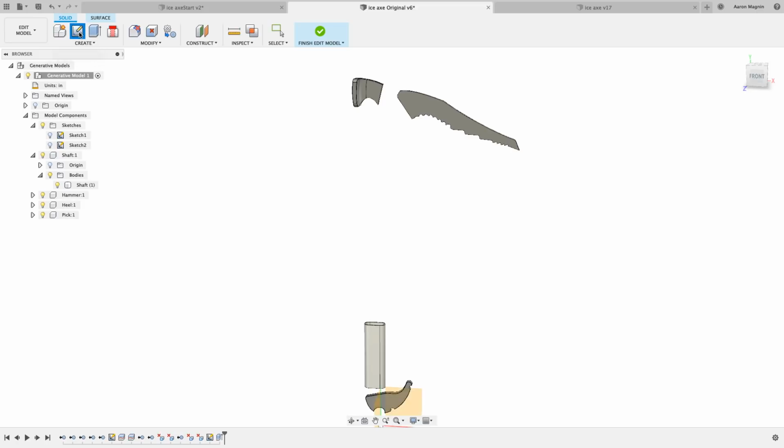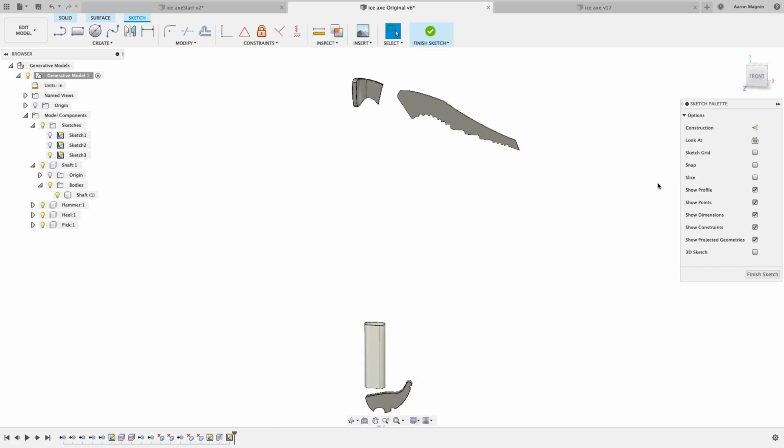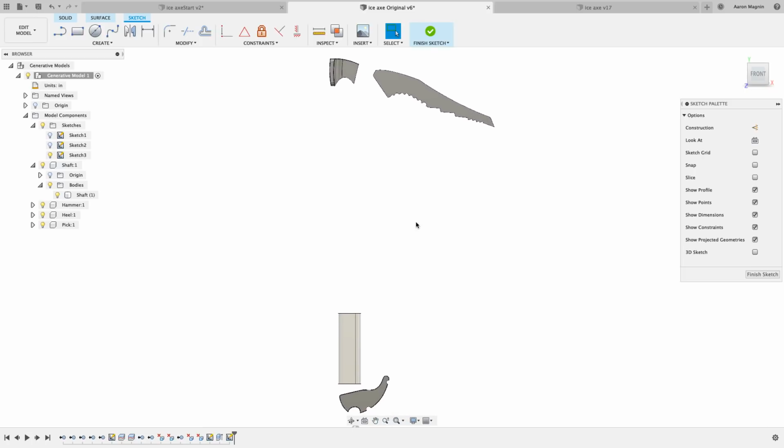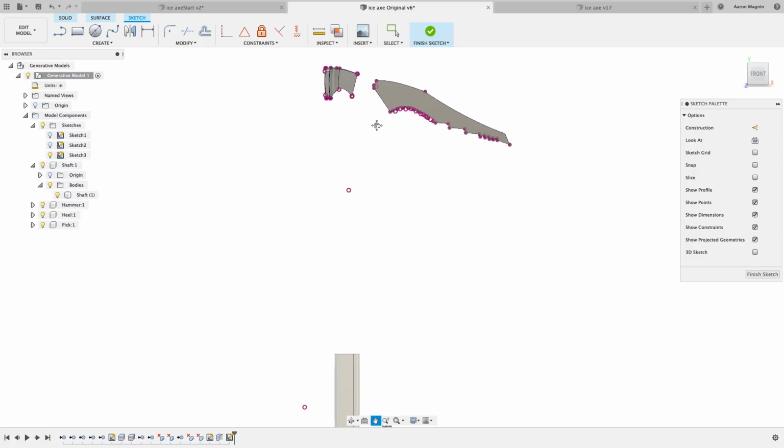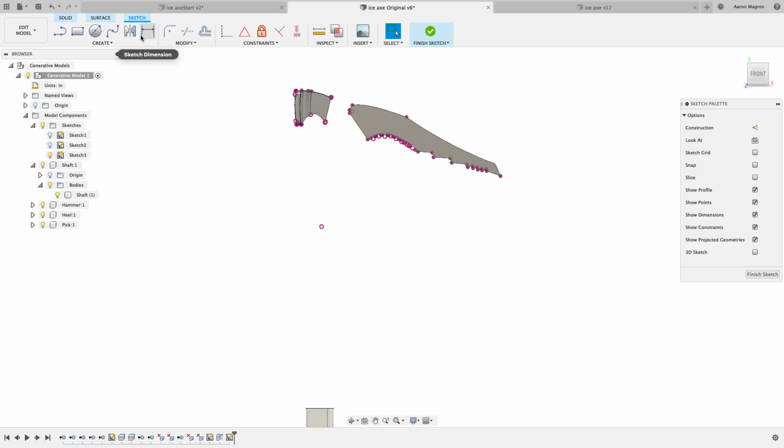So I'm going to create a sketch, and again I can use any flat face to begin sketching on, or the planes here at the bottom. And we'll look normal to this, and I'm going to start projecting pieces off. So I'm going to hit P on my keyboard, and to project these off very quickly, I'll just select this guy, and this guy, and there we go. We've created some sketches that I can use to kind of define these regions.